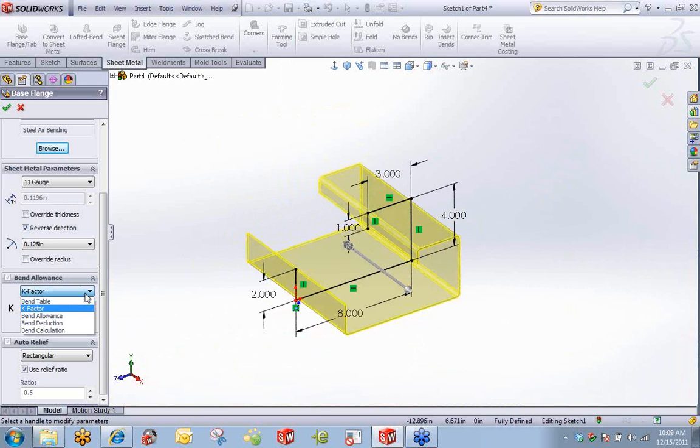Okay, and lastly, building in bend allowance, K-factors, bend deductions. You can enter that default value at this moment. Later, I can go bend by bend and choose different options. Or, this is new to 2011, you can load in a bend calculation table.